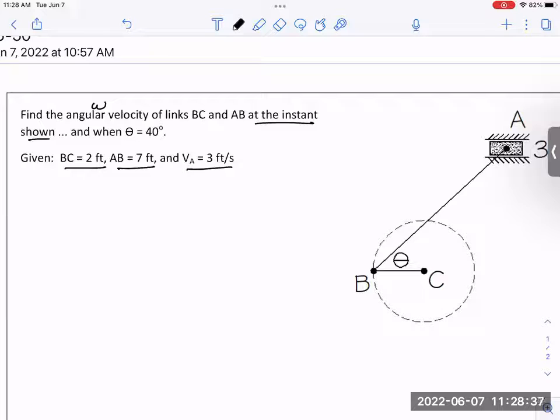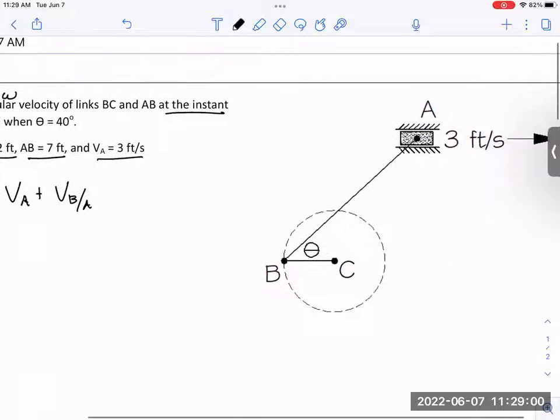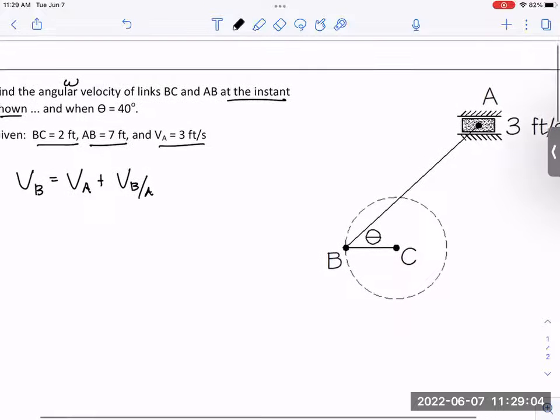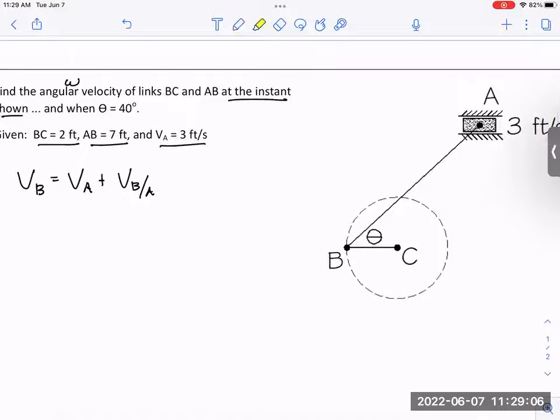All right. So let's see if we can survive this. We said the backbone equation here is that the velocity of B, the follower, is found by taking the velocity of A, then adding to it the velocity of B as it rotates around A to get back into position. Now I'm going to erase all this because it's going to make a mess of this drawing. But again, I want to redraw what the equation that I just drew there looks like.